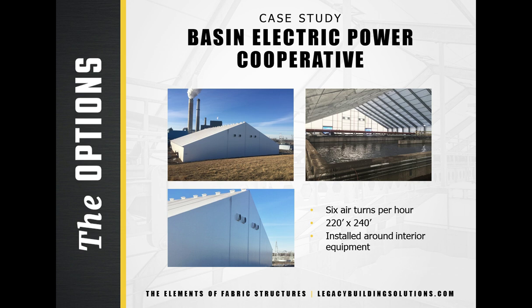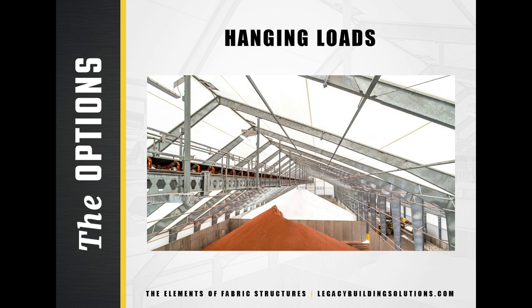Ventilation systems designed to reach specific airflow levels are especially common in waste and wastewater treatment buildings, like this bottom ash dewatering facility in North Dakota. It measures 220 feet wide by 240 feet long and uses a hot-dip galvanized steel frame. The ventilation systems in this building, including exhaust fans and ridge vents, are designed to produce 6 air turns per hour. In one picture, you can see the interior equipment, most of which is already in place during installation.